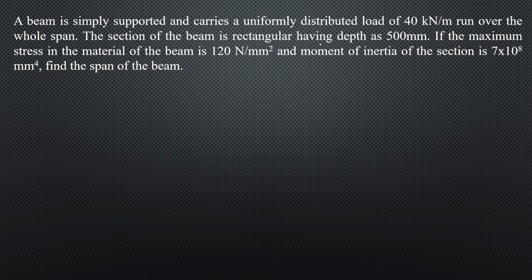The section of the beam is rectangular having depth as 500 mm. If the maximum stress in the middle of the beam is 120 Newton per mm square and moment of inertia is 7 into 10 power 8 mm power 4, find the span of the beam. So first of all, let's write the given data, all of us.